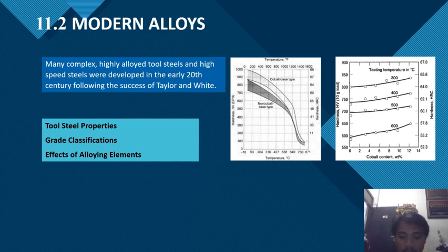And sulfur, in a normal concentration of 0.03% or less, has no significant effect on the properties of tool steel, and nitrogen is generally present in air melt grades in amounts varying from approximately 0.02 to 0.03%.